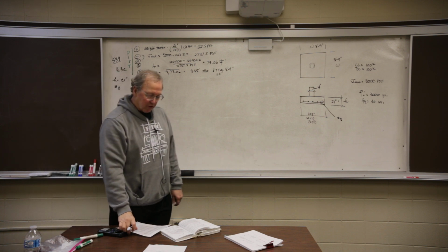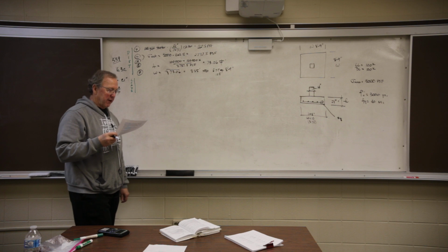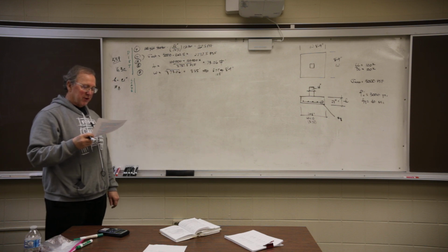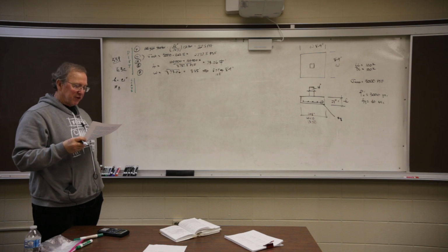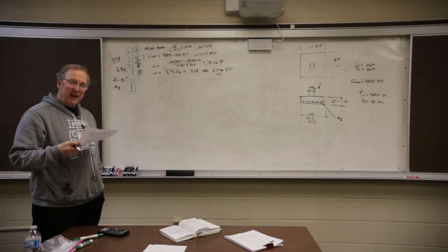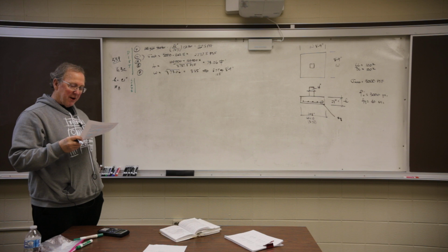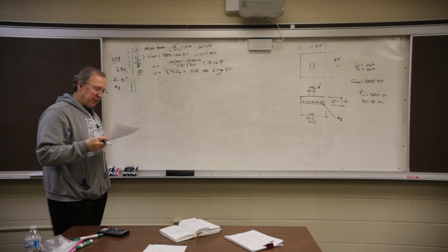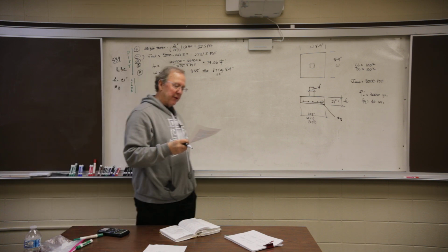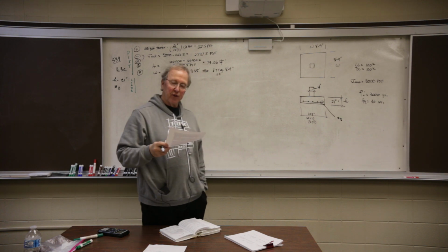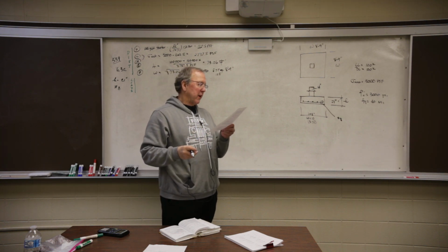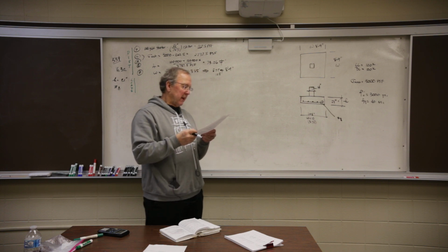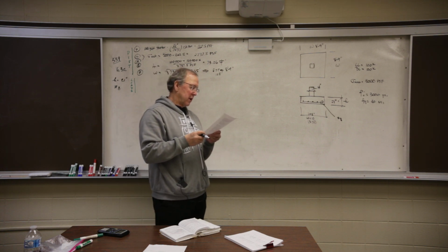Okay? So let's take a look at where we're going from here. Take the square root, round to the nearest 3-inch increment, determine the actual soil bearing capacity. Letter H is the check again. Don't need to do it if you're confident you did everything right. If you think you may have made an error, you might want to run through that calculation quick to spot the error. Letter I, determine the reinforcement we need for the factored loads.